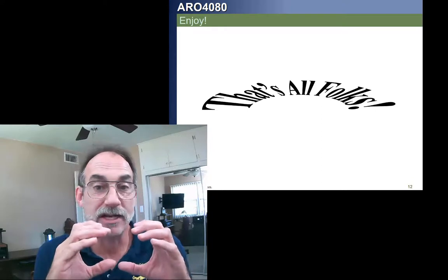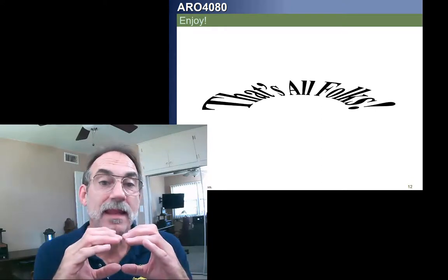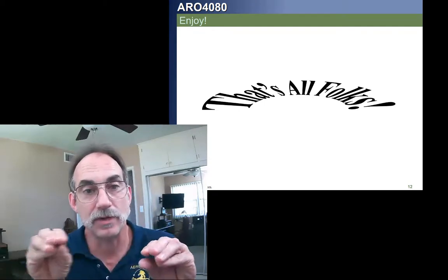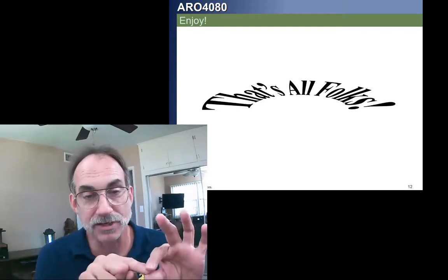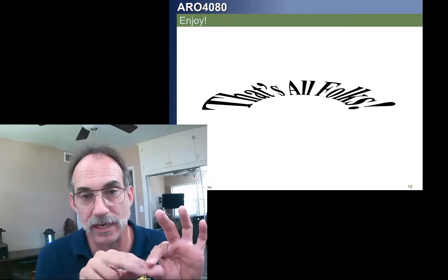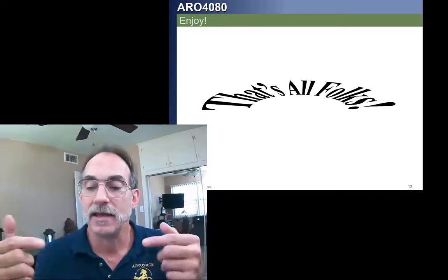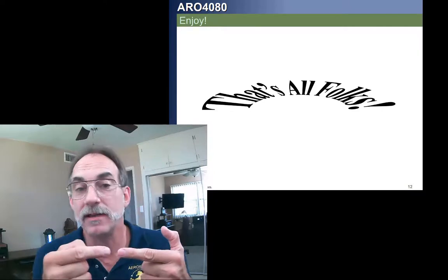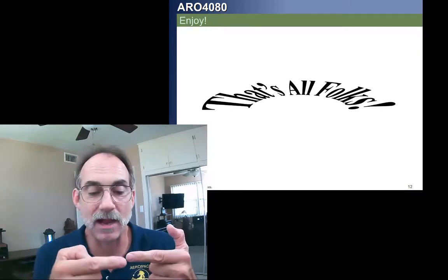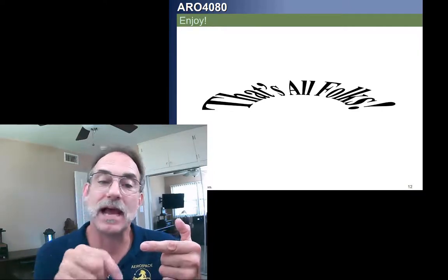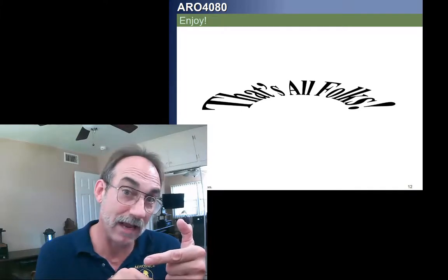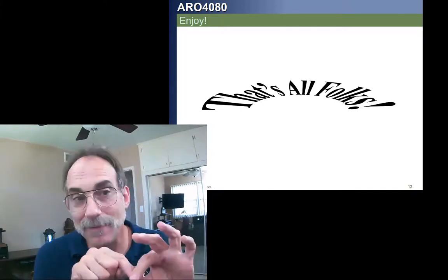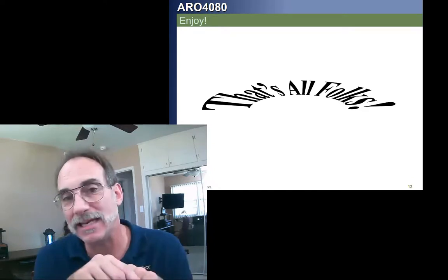Basically, we're going to change the local stiffness matrix. We're going to go through the process like normal. We're going to be careful when we pull the rotation. The rotation that we're going to get out of solving our system of equations is going to be the rotation of the element that has the hinge, but that didn't have the hinge modeled in that element. And then we will have to, after calculating the force in the element, back solve to calculate the angle of rotation of the same node in the other element, if we need to do that.